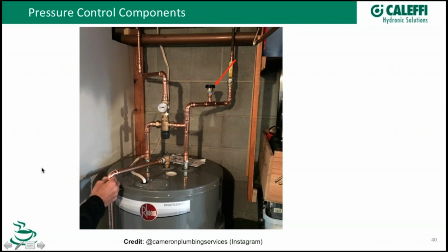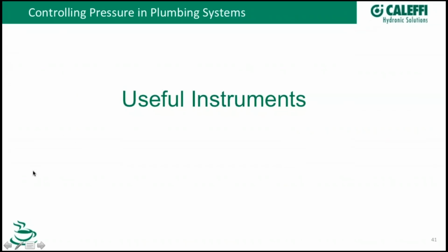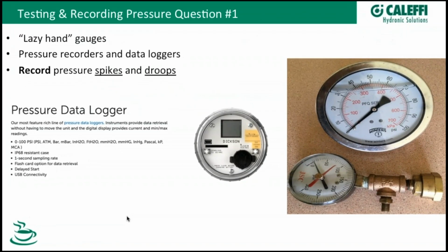I thought I had a picture of that in here. So it's not just the tank itself that will collapse, you could actually collapse that flue pipe going up through the center of the tank, and now the burner kicks on, and you've got an issue with flue gases not going up through the pipe properly and possibly spilling in the room and causing a CO issue. So that's where this device gets added in for that protection. I don't see them that often, to be honest with you, but I see pretty much every application those folks do, they put one on there. Maybe their local jurisdiction is requiring them, or the inspector that inspects that job.